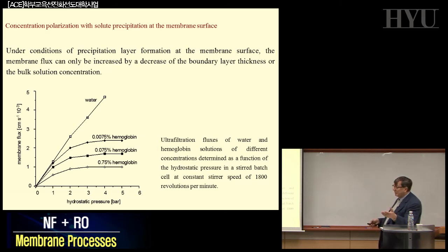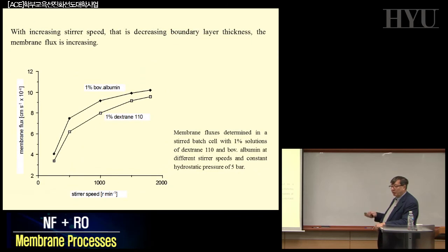And this, for a real application, is quite interesting and important, because it makes no sense to go on increasing pressure if the transmembrane flux does not change. So you want to know at which point, for each concentration, you have a deviation from linearity. That is one of the parameters we want to understand, and that's what we call the critical transmembrane flux. This is the limit transmembrane flux, the highest value that we can have. The critical one is when we start to have this deviation from linearity. Both of them are quite important for any industrial application and development.